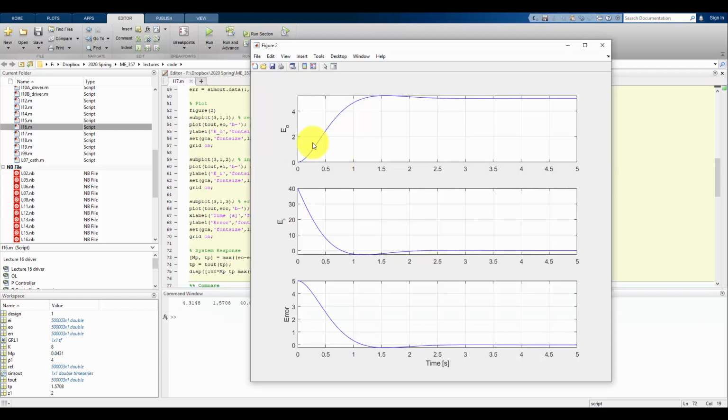All right, so we see graphically what the response is of the output voltage. It comes up to some peak. I'll just let MATLAB figure out what that value is. And then it comes down and it's going to be steady at 5 volts. So the first thing the controller is supposed to do, does it drive the output to that constant 5 value, which is to say, does it drive the error to 0? Yes. So it does do the first job that it really has to do, drive the error to 0. We see here graphically that it requires a maximum input effort of 40. If it's an electrical system, that would be a 40 volt peak. Maybe that's too much. We'll have to investigate that separately.